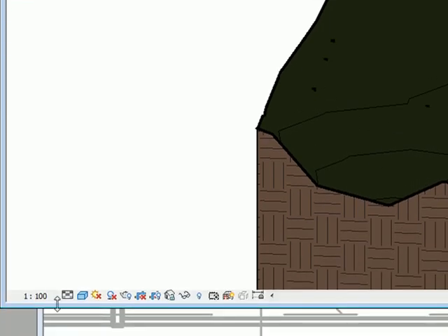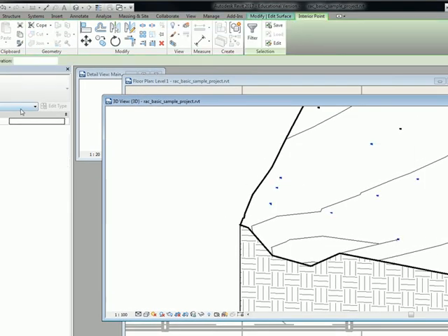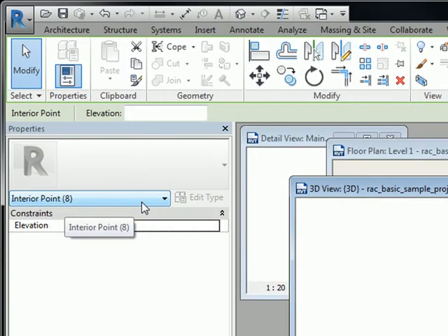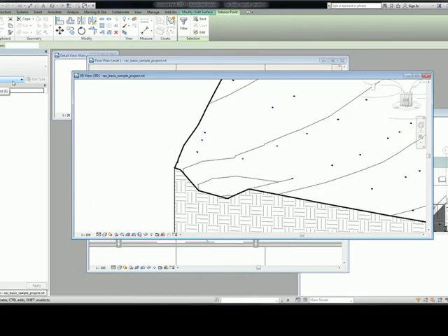Hang on. So how do you actually get the topo in? We'll talk about that. Basically what I do for mine is I'll take a CAD file and link it in, and then I'll just go point, point, point, point, point along the thing, then select them all and put them at the right height. For really complex topos, it's really not efficient. I'm sure there are better ways out there. For some reason in my career, I've mostly worked on flat sites, so I haven't had a need to become an expert in it. But we'll work on some topo stuff for sure.